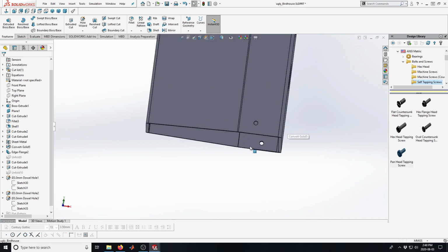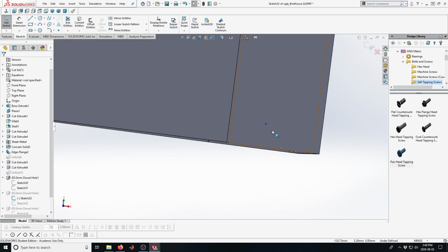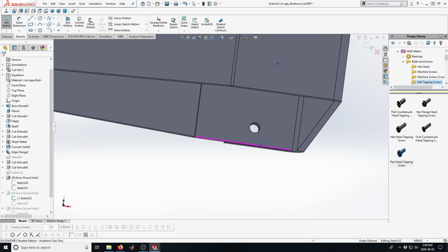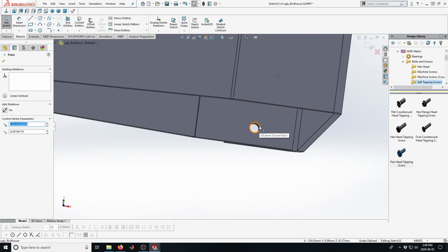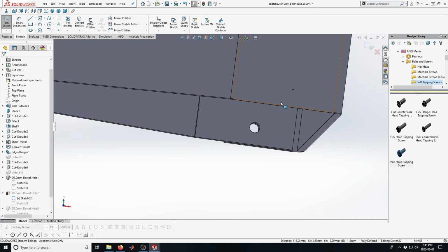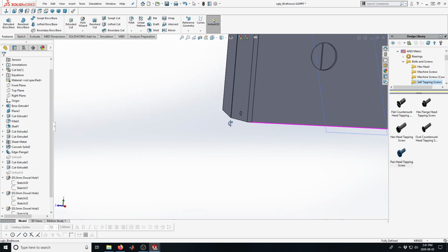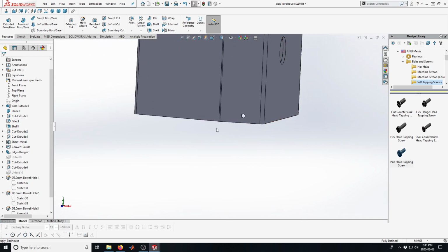Now this one, it's kind of off here in its own world. I just placed it. So like every sketch, I can edit that sketch, and if I go Control there, I can make that point on this sketch concentric with the first hole that I drilled. There. So now I've got 4 holes that will hold screws that will hold my bottom on.